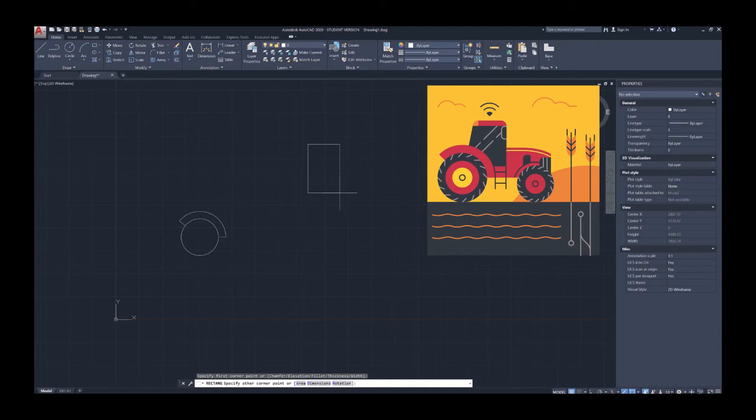As you can see, you can press A for area. It's those blue capital letters on your keyboard that you press to choose that function. So I'm going to choose D for dimension, okay. Now the length. Always remember the length. I'm going to choose length, which goes horizontally across your page, to be 500. Press enter, okay? Now you've got your width, which goes in the vertical direction. I'm going to choose that to be 1000 and press enter, okay?